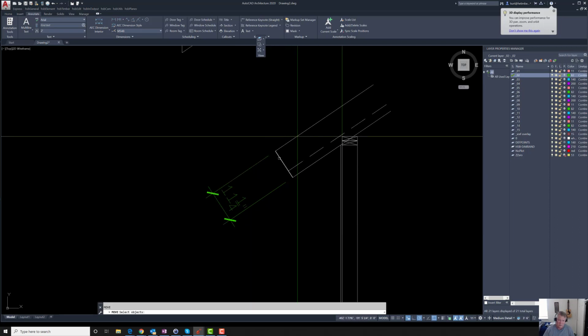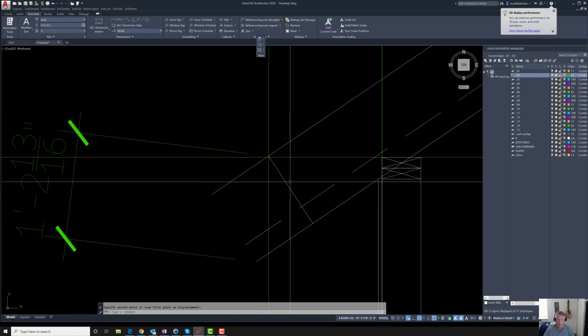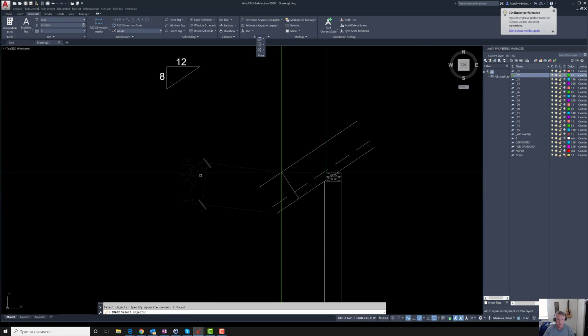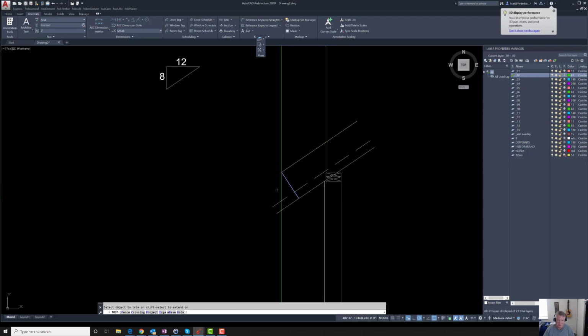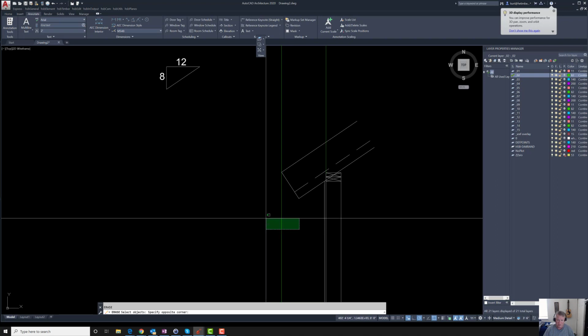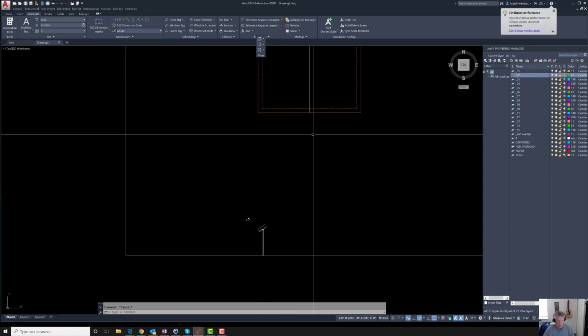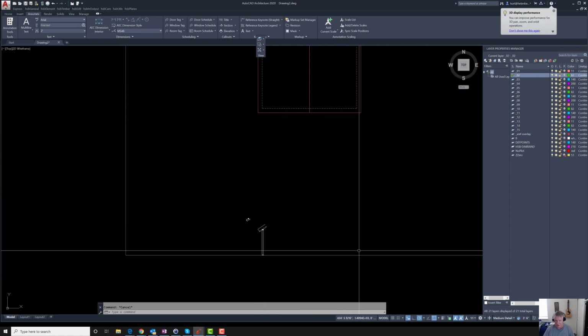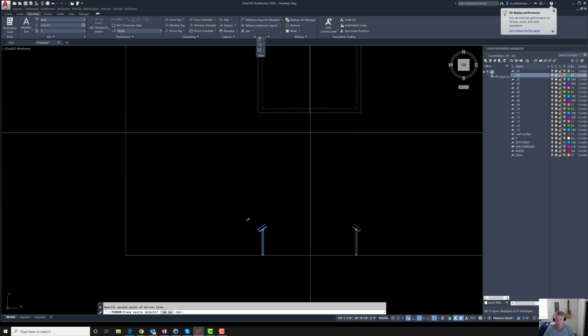So I will just move my fascia line back to this intersection right here, and now we don't need the dimension, and we no longer need that. And I will just simply trim some things off to clean it up here, and I'll erase the vertical lines that we put in because now I've placed that wall at the correct location. I want the same condition on the far side, or on the other side. And I know that that mirrors around the ridge, so I can just simply mirror around the ridge and then use some quick AutoCAD tools for filleting two lines together.